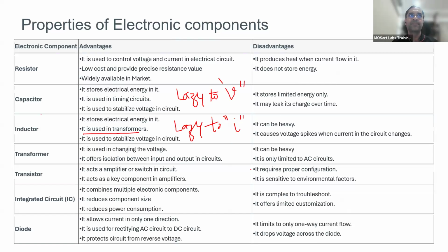Third week. And very powerful. Inductors are very powerful in all the high current applications because they don't allow the current to spike whenever you have a short circuit. Having this inductor means that your current will still be limited, right? So these inductors or transformers are very powerful. Okay, but they are bulky components. They have weight. So typically these are used sparingly and only when you need it.